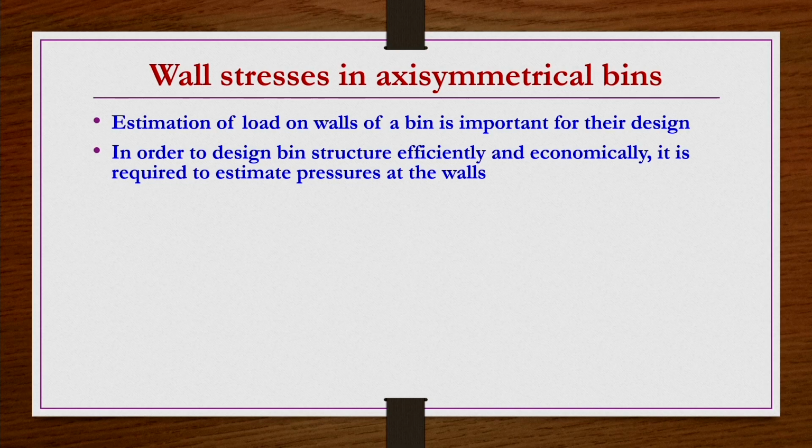So, based on this pressure distribution, or how much pressure is there on the walls, one is going to decide how much material one can store in a container, and what flow rate one can take the material at, because both the static and dynamic conditions are very important, and both of them have an effect on the pressure on the walls of the bins. So, that is the reason this pressure calculation is going to be very crucial in the design of these solid storage vessels.